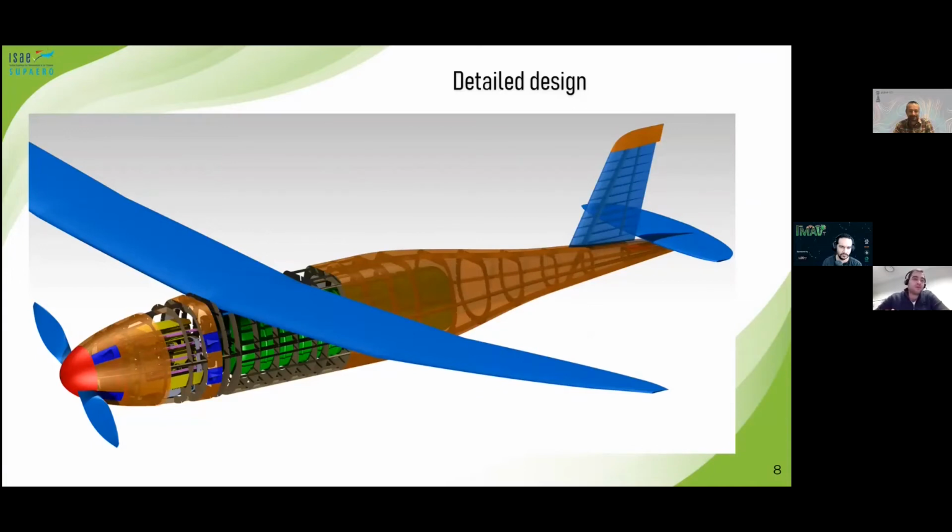In front, what you can see is the system of air inlets, NACA inlets, which serve to inject air inside, which is used for the fuel cell, both to feed the fuel cell with oxygen and to evacuate the heat which is generated by the fuel cell. The fuel cell you can see as a yellow box here. This is a configuration with a liquid hydrogen reservoir. So you can see in purple a small heat exchanger, which has the task to slightly heat up the very cold gas which is leaving the liquid hydrogen reservoir.